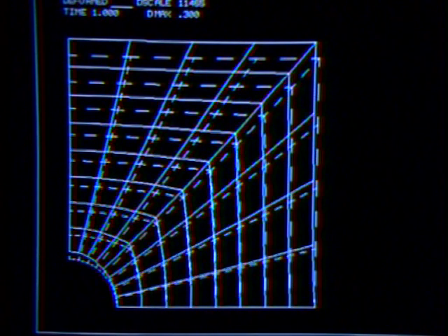Of course, the deformations are magnified. Note that, as expected, the top face has uniformly moved up. However, note that the nodal points on the horizontal symmetry line have not displaced at all. This is quite unphysical and shows that the wrong boundary conditions have been used.